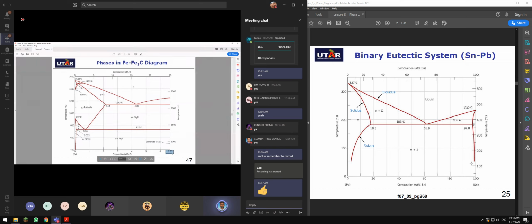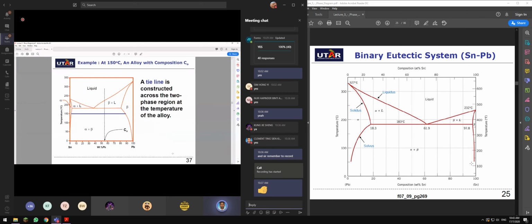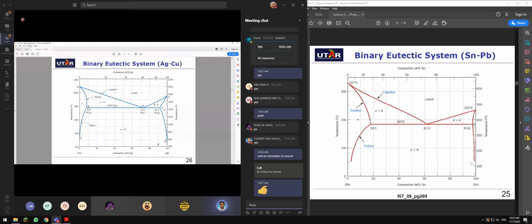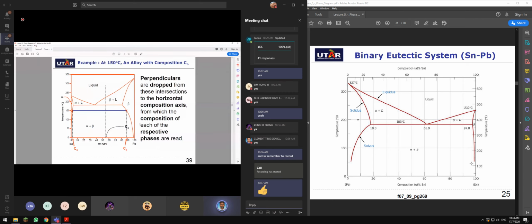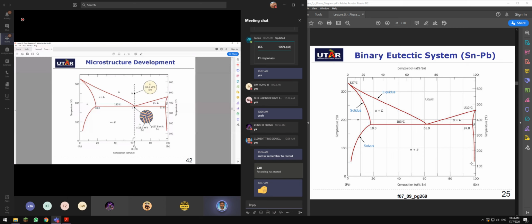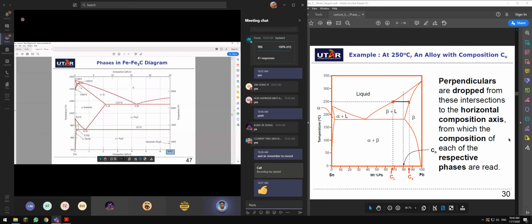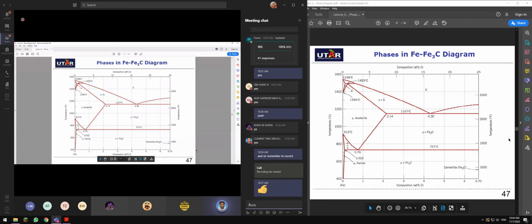Can you see? Whereas all the examples before this, you have 100%, right? Here 0 and here 100%. And the pure materials stick to the portions on their side vertically. But if you look at the iron carbon phase diagram, it is 6.7% only. So it means that yes, you have 7%, 70% and 100% here, but it has been chopped off because all those are graphites.